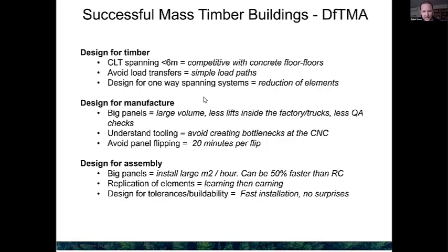So firstly, designing for timber, from our experience, if we're designing with CLT specifically, spans up to 6 meters, we're really competitive with concrete. We can be shallower than concrete, and our floor to floors that we're used to will be achievable with CLT. When it comes to XLam, it's about to the 9 meter range we can get to. So designing with the material first is super critical, like understanding how concrete buildings work. We've got post-tension flat plate slabs going two-way action. It's a very different product we're working with than timber is.